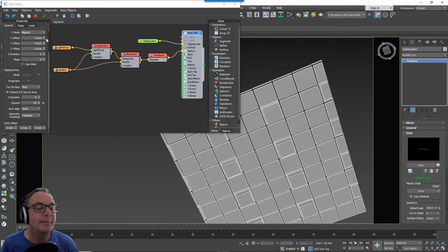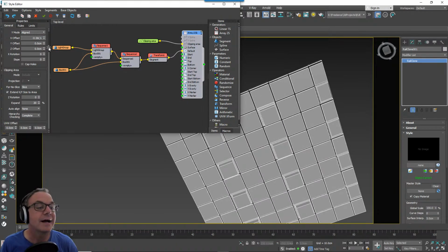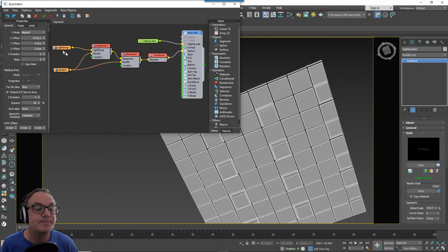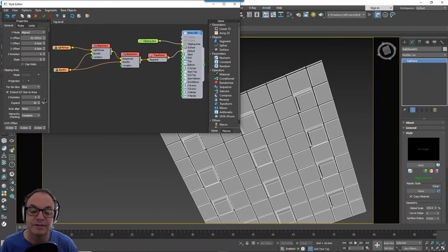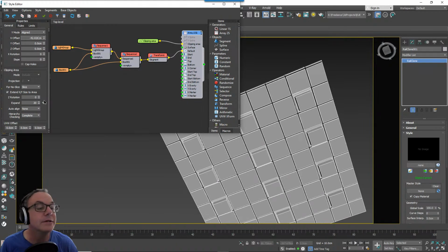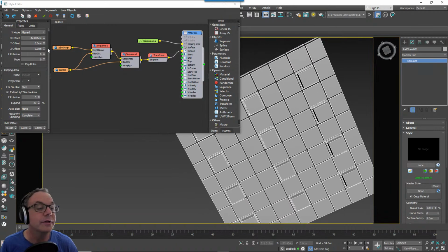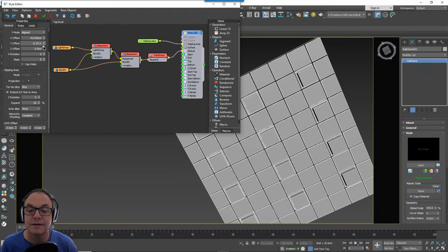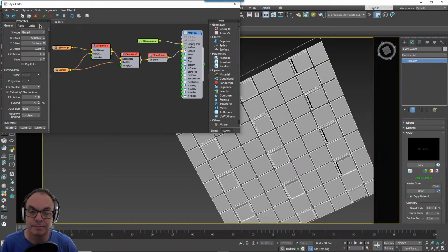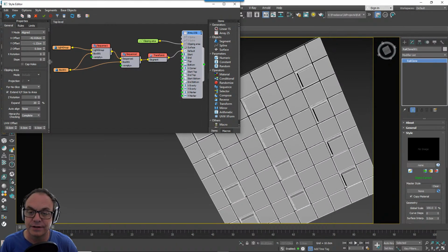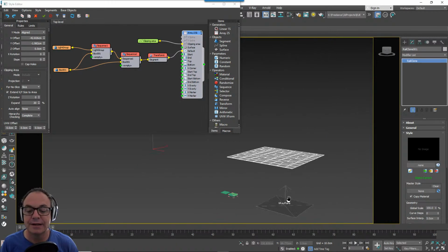What that means now is that I've got a little bit of wriggle space if I use the X and Y offset, as you can see here, to maneuver this around. So you can see I can center that a little bit more by using that X offset like I've just done, and the same on the Y axis. I can do the same thing because I've got space outside of the array that I can use to center that. So that's quite handy.